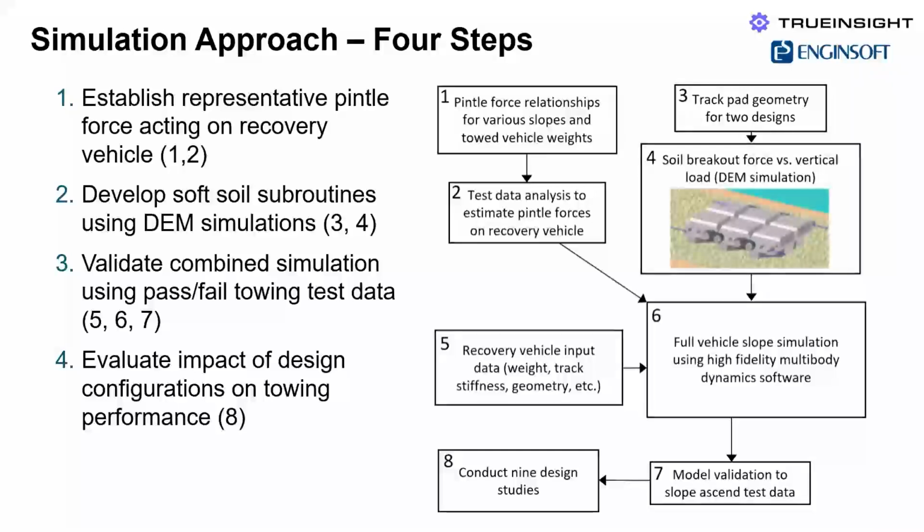In this case, since the soil behavior is fairly constant in different locations in space, what we wanted to do was to characterize the soil as a function of normal force pushing down on the track, and also the side to side or front to back forces that are trying to break the track free from the soil. So blocks 3 and 4 are looking at that, and we had 2 different track pad geometries to look at.